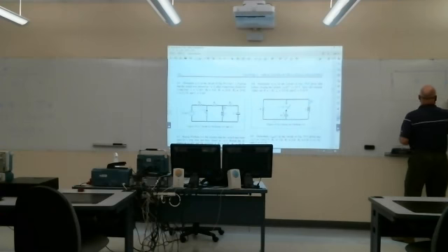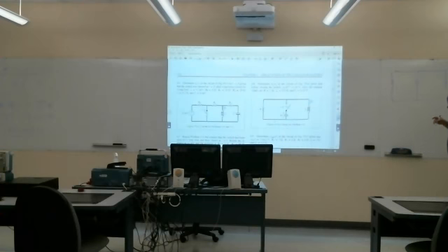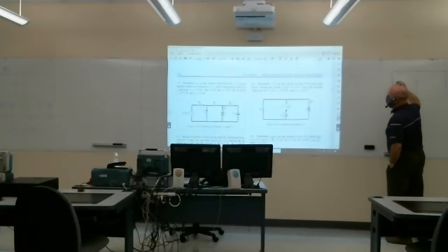And then the way we handle the initial condition, you can do it either of two ways, with a voltage source in series with the capacitor, or a current source in parallel with the capacitor. It doesn't really matter. Let's get the element values in here.